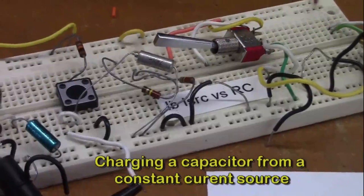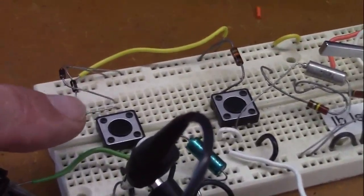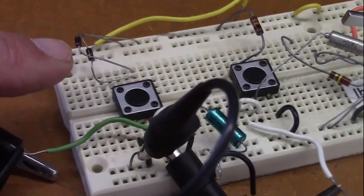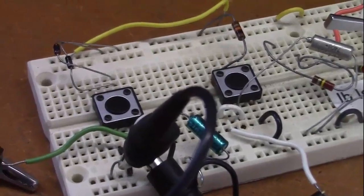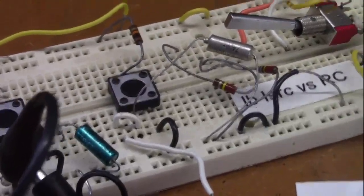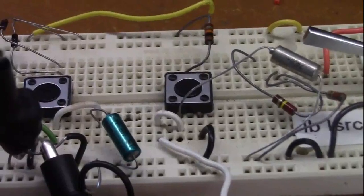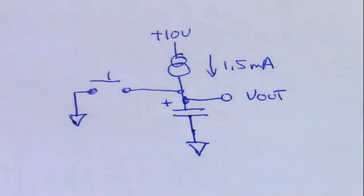So what we have is a current source. These are special diodes that allow a constant current through. Each one is 0.75 milliamps. We have two of them, so we have a 1.5 milliamp current source. And we have a capacitor. The capacitor is connected to the current source and ground. We also have a push button. That push button is connected between the capacitor and ground. It's in parallel with the capacitor. So our experimental test setup looks like this.